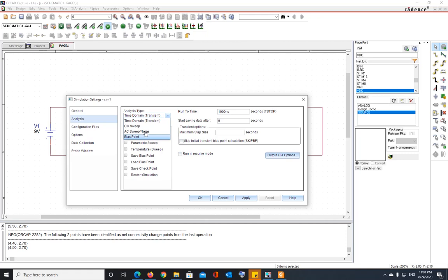So when you change the frequency of the source, generally your circuit output or circuit values, if the circuit has electronic components or analog components like capacitors or inductors, the values of voltage and current at different frequencies are different for those types of circuits. If you just have resistors, in general, ideally, the resistance does not change with the change in frequency. Actually it does change if your frequency becomes quite high.